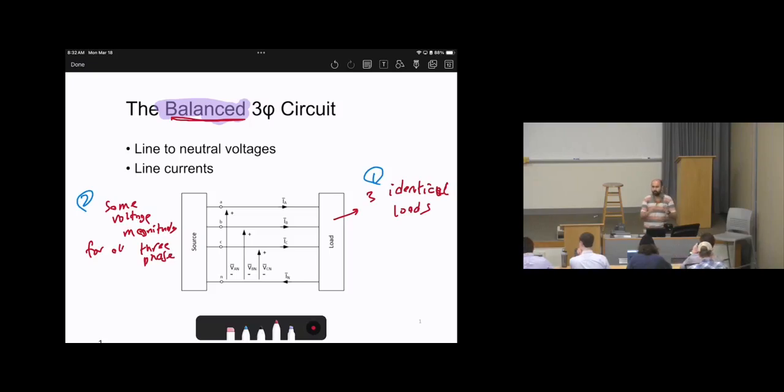Which means if phase A, if your home is connected to 120, your neighbor must be 120, the other neighbor must be 120. And that's normal, that's what's supposed to be. The third thing, which is phase shift 120. This is a must. Phase shifts 120. How do we get 120? It's basically 360 divided by 3, then it's 120 degrees.